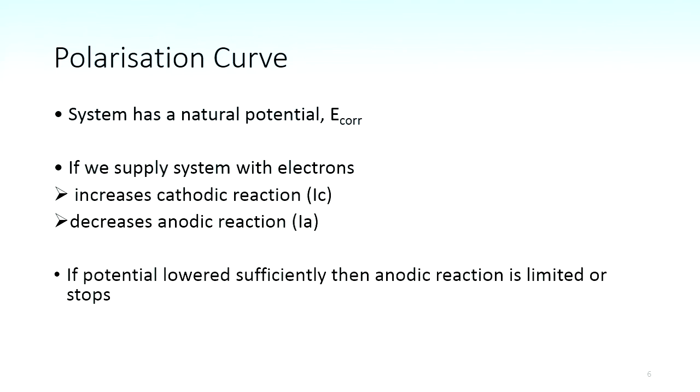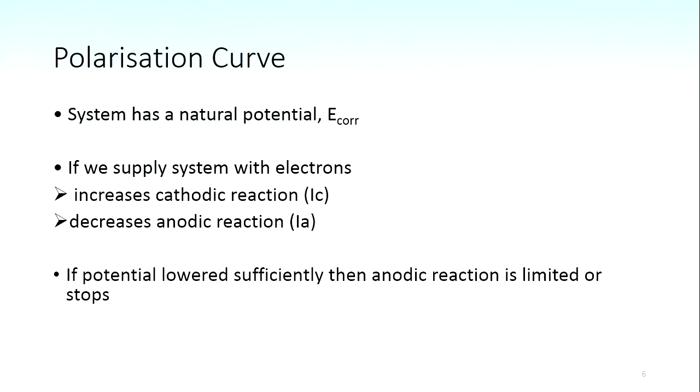So the structure at equilibrium has an anodic current flowing through at that free corrosion potential. And the magnitude of that current can be influenced by changing the potential. We'll talk about the magnitude of the potential later on, but you want to significantly reduce the corrosion.